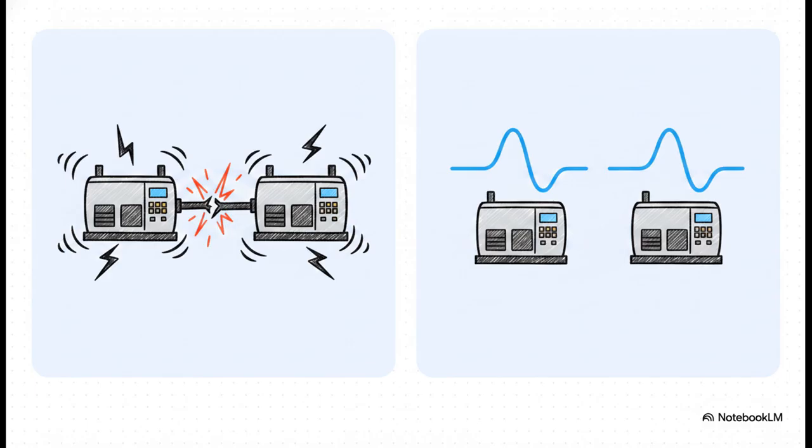Compare it to asynchronous control. Asynchronous mode is great because it holds frequency perfectly flat, but it relies completely on an active data link between all the governors. If a comms cable breaks mid-voyage, say from heavy engine vibration, asynchronous control fails instantly. The whole system breaks down. Speed droop survives because every generator operates independently.